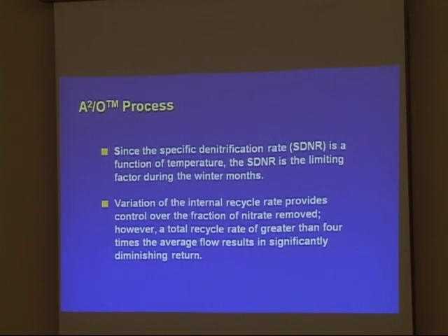Alright, then you've got specific denitrification rates, a function of temperature. That's going to be your limiting factor during the winter months. Temperature starts dropping, you start losing it. And as we saw this past winter, it was pretty cold. You know, this plant lost it. There are other plants I've been involved with, some in Connecticut, same thing. You get into brutal cold weather, and it's very difficult to maintain nitrification.